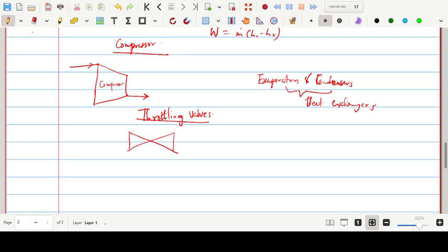Okay, let me clean this. Okay, perfect. All right, so here it enters, then comes out here. So there are process 1 and process 2, or you call it stage 1 and stage 2. This is a throttle valve. So the formula for a throttle valve is simply Z1 equals Z2, so if you consider it, it will be 0. So work done is 0. It works under adiabatic condition, so this is 0. If all these are zeros, what do we have left?